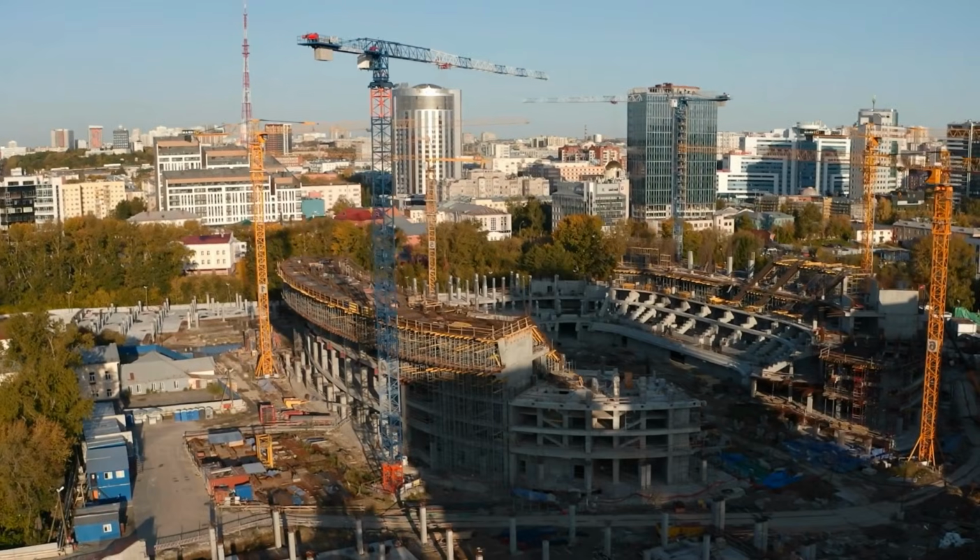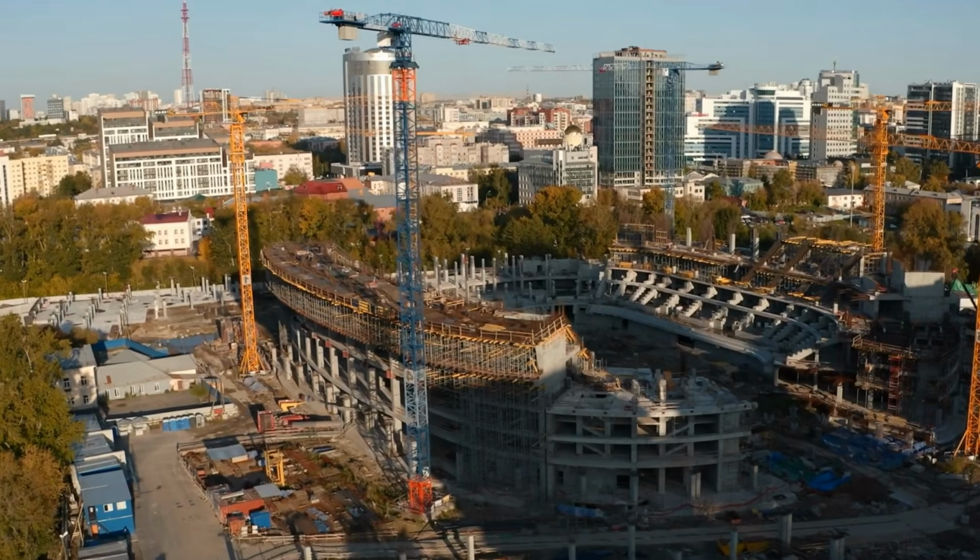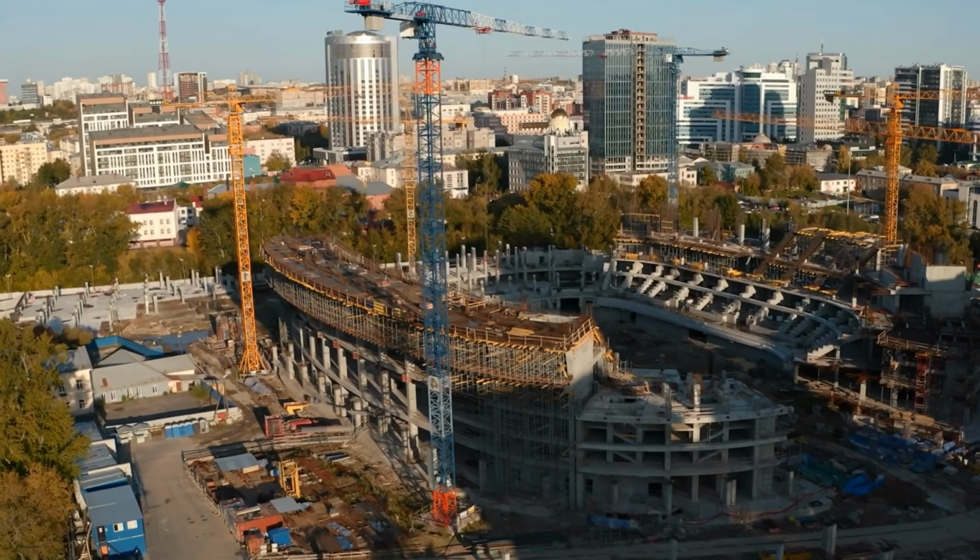It depends. For most projects, that distortion amount is probably acceptable, but if one were performing high accuracy layout for an engineering project, you could get yourself into some trouble by allowing 0.05 of a foot of systematic error over 1,000 feet.